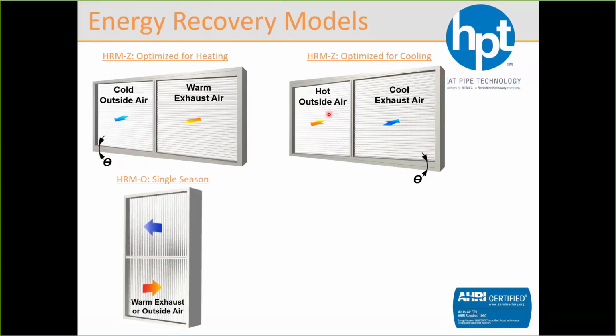So say if you want to get heating recovery, what you need to do is you need to make sure that that exhaust airstream is on the bottom. For summer recovery, vice versa, you want the supply to be at the bottom because that's going to be your outside air or your warm airstream during summer.